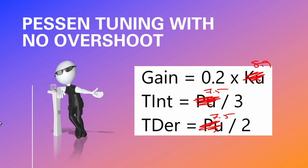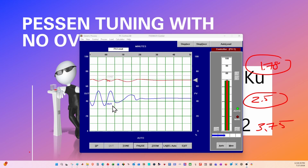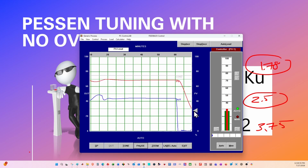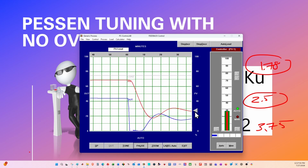Now, if I work that out very quickly, I should get the following results. I have got a gain value of about 1.78. I've calculated my integral to be 2.5, and I've calculated the derivative to be 3.75. Let's put them into the controller. And now that the values are in the controller, we can try it out. I'm going to drop the set point down and we'll have a look at the response that we can achieve. It is going to give me less overshoot than what we would have had with the previous example that we did.